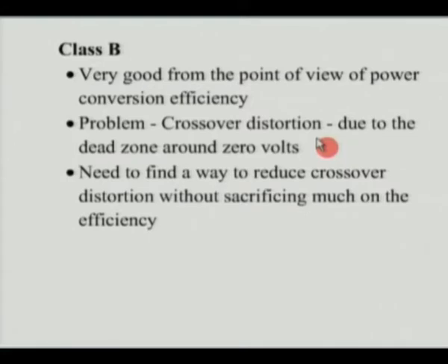Dead zone meaning we had a region, that region was plus minus 0.5 volts, when the Vi is within plus minus 0.5 volts. We saw that during that period we had the dead zone, meaning we have no output. So because of this we would have what is called crossover distortion. Now crossover distortion is extremely disturbing. I would suggest it's a very, very good idea to design a very simple emitter follower like the one which we have done.